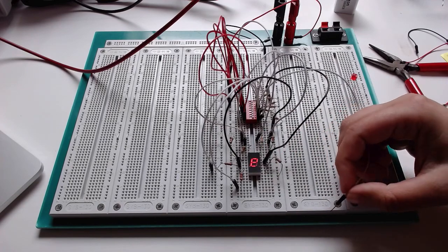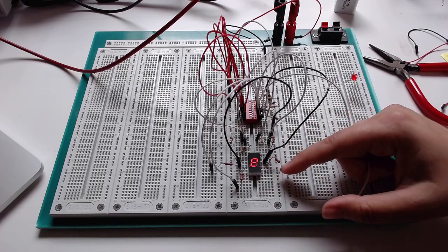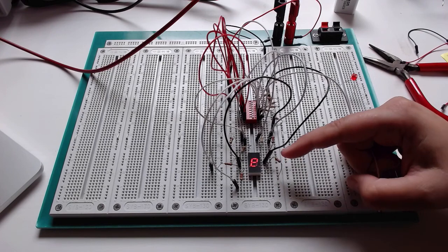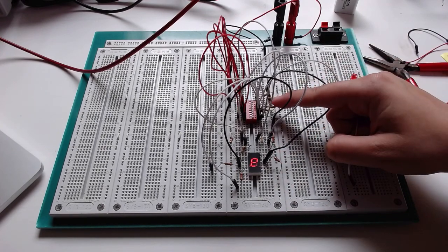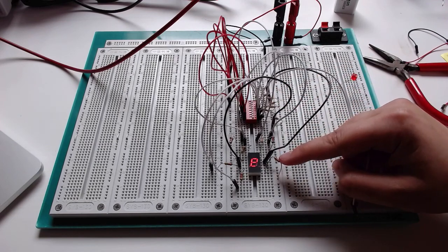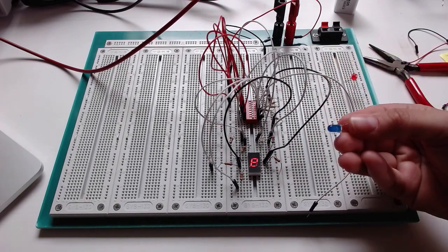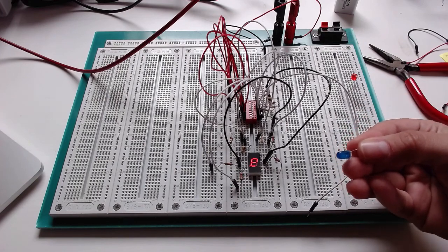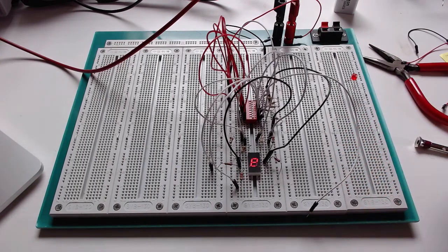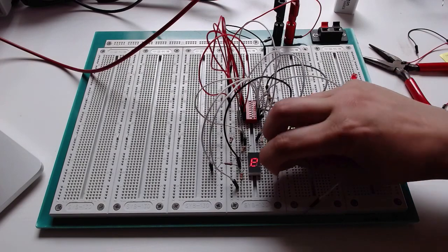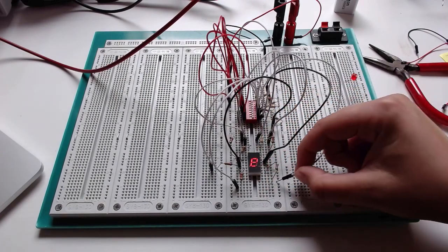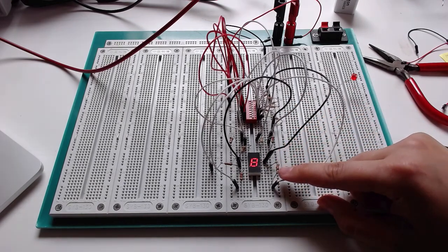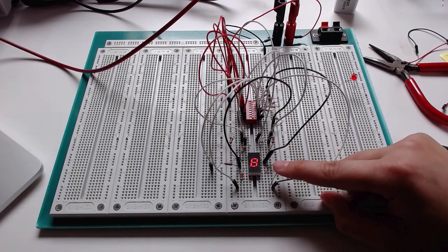Another issue that I'll see is that students will take the resistor and they'll just shove one end in ground or power. I don't know which. They'll just pick one. Now we're used to seeing resistors that connect to ground because that's how we do our pull downs. And honestly, it's how we do our individual LEDs. And it's okay when we have an individual LED because the other end of my LED is going to a signal. But here it's not okay. I don't want to directly drive that pin. I need to have it conditionally lit or not lit. So I cannot take one of these ends of the resistors and plug them directly to power or ground.